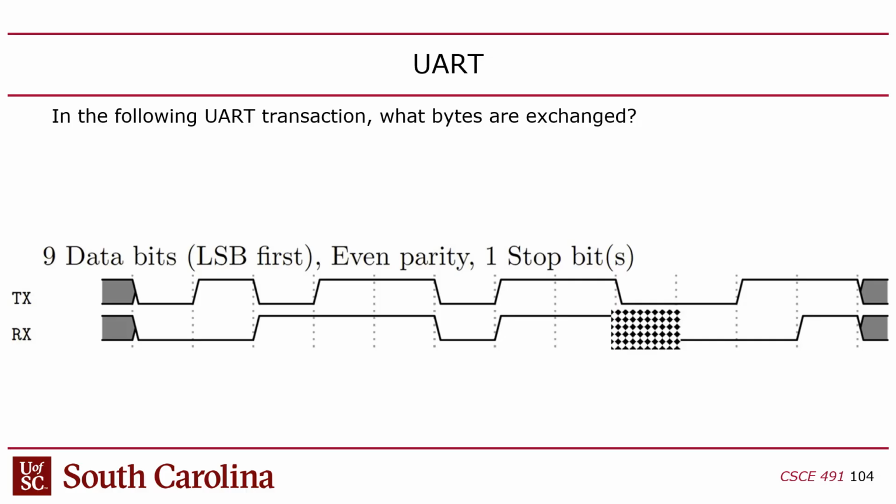So that's the reason why no one talks about baud rate versus throughput for SPI. It never comes up. Why? Because SPI doesn't have any protocol overhead. But UART does, because you have to tack on extra bits for every single word you send, right? Does that make sense? Okay, so the baud rate is the native signaling rate of the channel, whereas the throughput takes into account the overhead. In this case, the throughput is 9/12 of the baud rate, because you have to put the start and stop around each individual value you send across the channel.